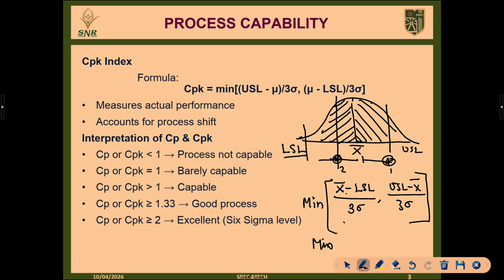Here we can see that when the CP value or CPK value is less than 1, the process is not capable. We can directly say that for the CP value we have calculated and the CPK value we have calculated, if the calculated value is less than 1, it purely indicates the process is unstable. At any point of time, or presently, defective pieces will come, the process is not stable. Next one, when the CP value or CPK value is equal to 1, the process is just capable of producing the specification. In case of any mistake, immediately it will come out of the process and become unstable.